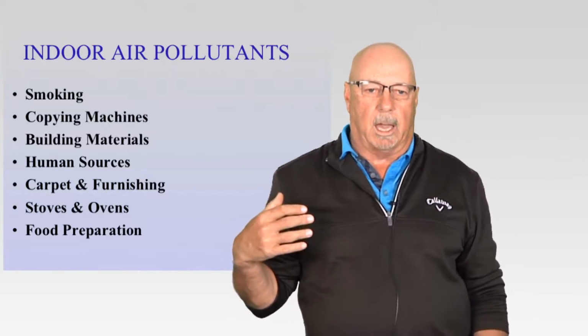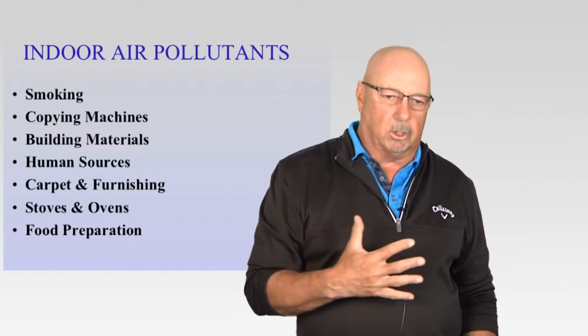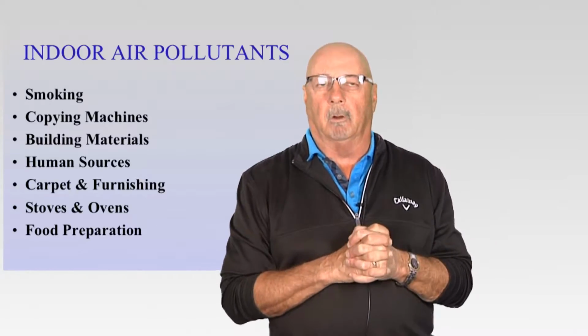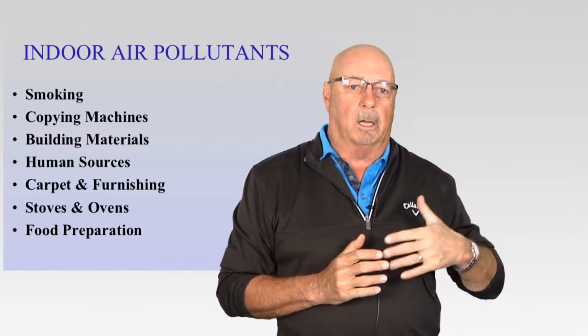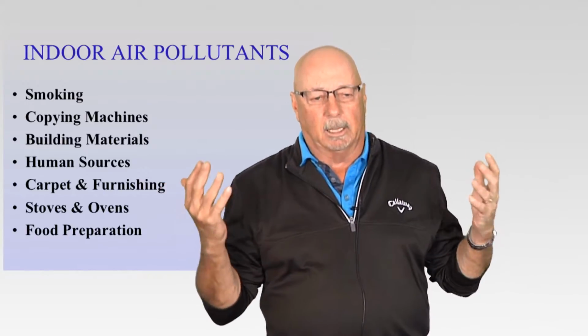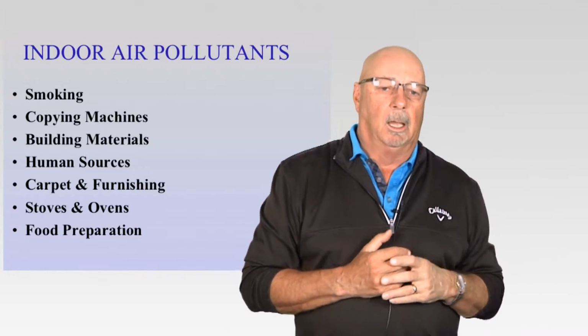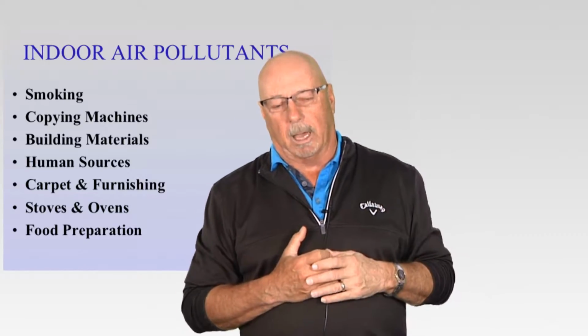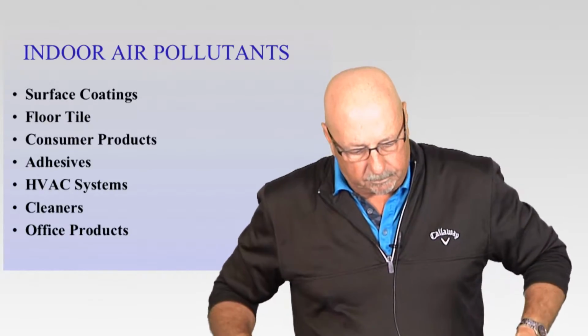Any areas where we've got stoves and ovens where cooking can take place, and just food preparation. Whenever I have done indoor air quality inspections and I walk in the front door and all of a sudden I can clearly smell the aroma of coffee, or another good one is popcorn, that's telling me right away that I'm able to pick up those odors so readily that I don't have good ventilation going on in this building. And so I do probably have an indoor air quality problem that needs to be addressed.